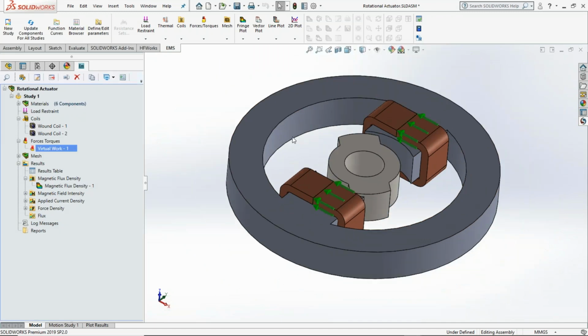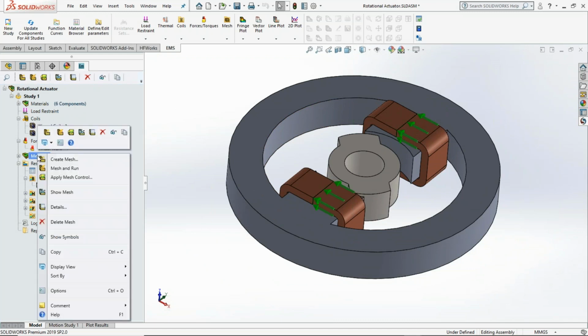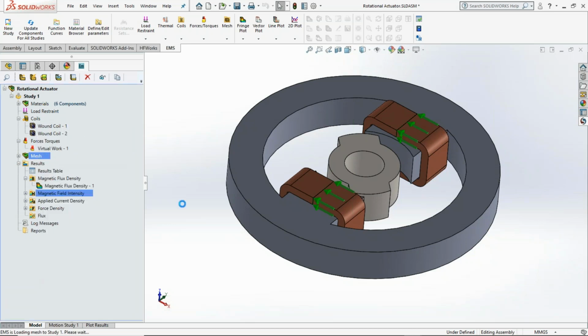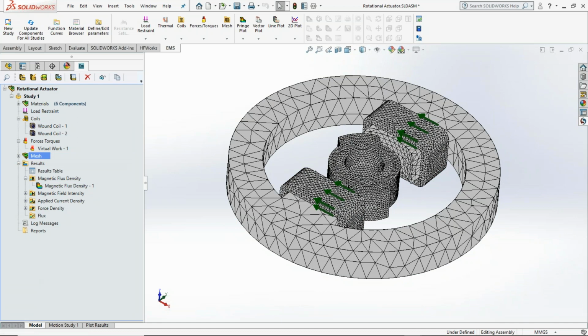Once the simulation is complete, we will take a look at the results. Okay. Now, the second important thing, I mentioned two important things to do in EMS simulation. One is the air geometry, and the second one is the concept of finite element mesh. We use a technique called finite element analysis to solve the electromagnetic equations, and hence it's very important to discretize or break up this problem into small finite elements, and that is then done automatically using the EMS meshing